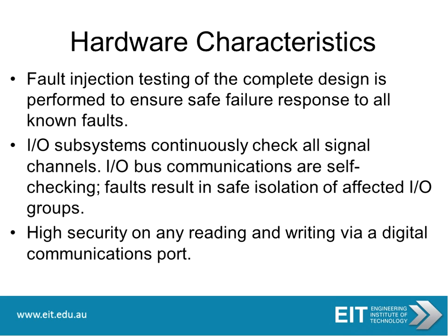Now, if you look at hardware characteristics, fault injection testing of the complete design is performed to ensure safe failure response to all known faults. Input-output subsystems continuously check all signal channels. Input-output bus communications are self-checking. Faults result in safe isolation of affected input-output groups, and we have high security on any reading and writing via the digital communications port.